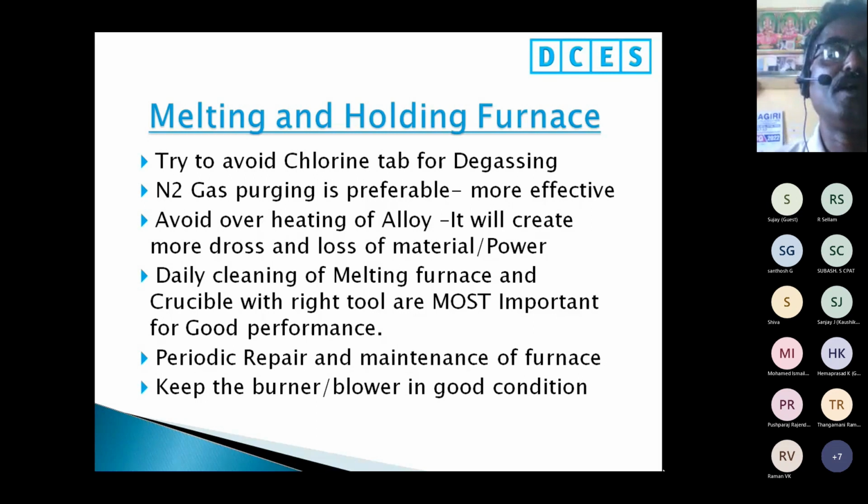And avoid overheating of the alloy. It will create more dross and loss of material. This also happens on the shop floor sometimes. So we have to insist that the operator not overheat, or else make a cut-off in the furnace.